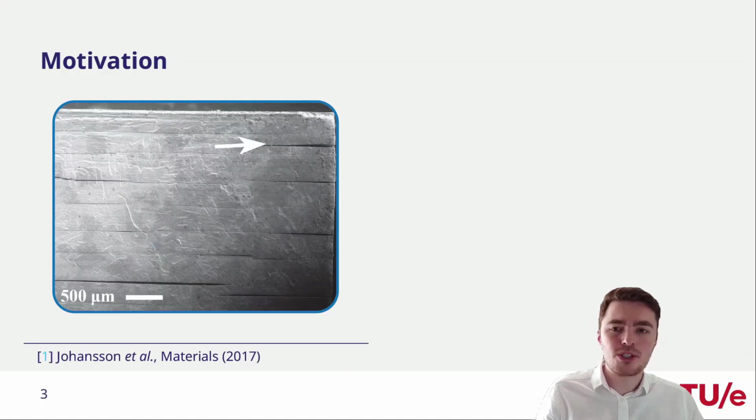However, at the microscale, defects such as delamination are often still present, and problems at this scale deteriorate the material properties of the end product and therefore prevent the widespread adoption of photopolymerization in the high-tech industry. In essence, the main unresolved issue is the insufficient consistency and repeatability due to, for instance, variability in the printing process, variability in the feedstock materials, and variability in the equipment.